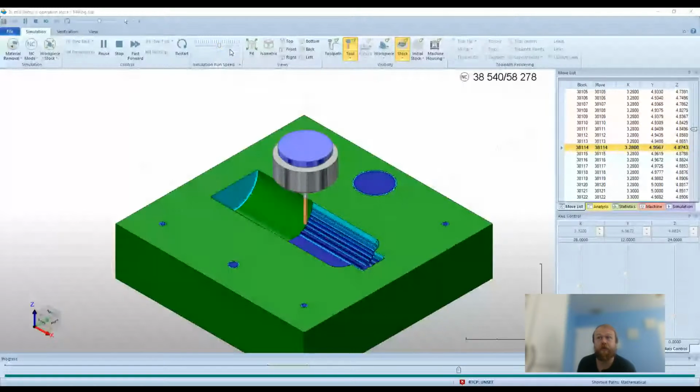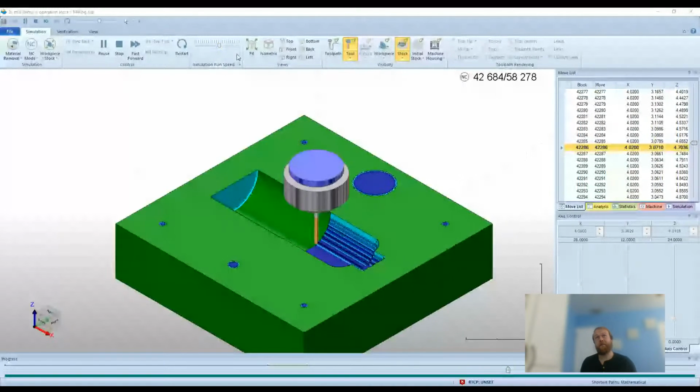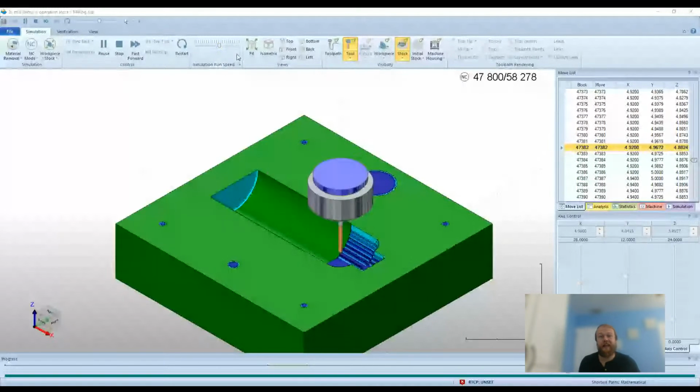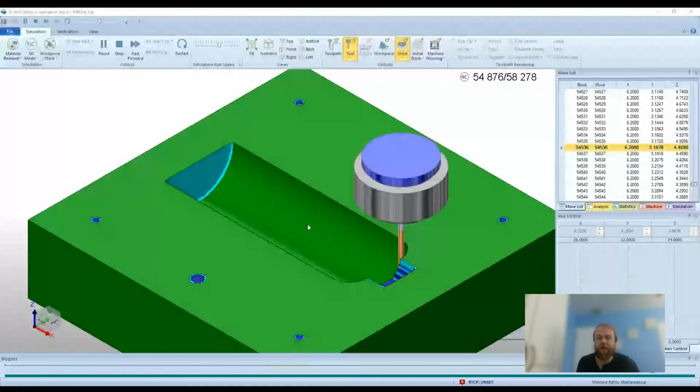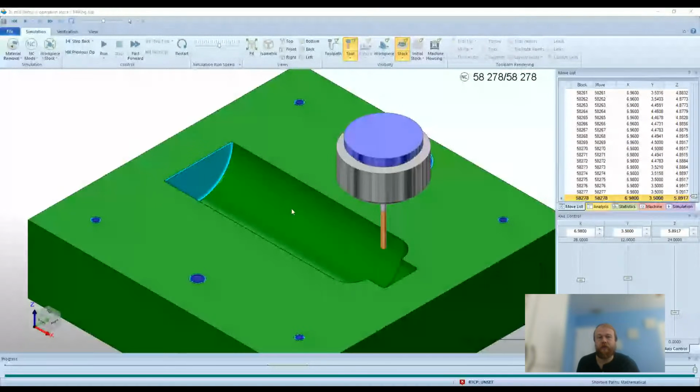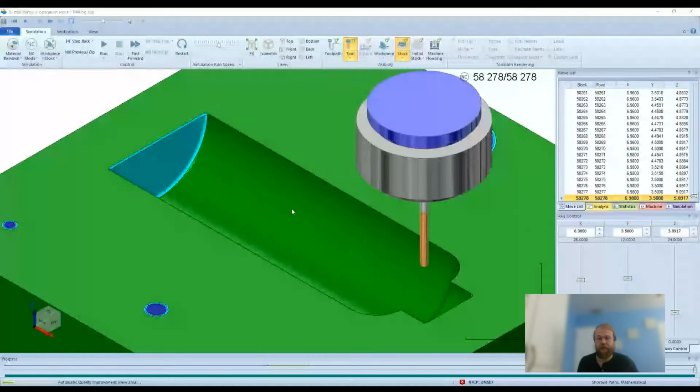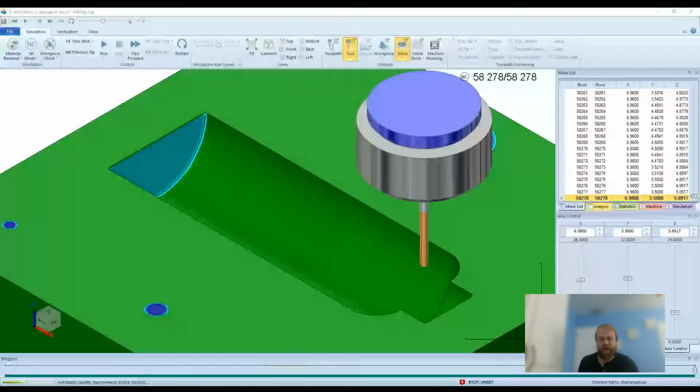We also viewed how to begin modeling, defining a new machine and defining the components of that machine, the spindle, the table, and everything else that we're able to define there under the machine definitions page. Also the limits in X, Y, Z, and A-axis movement.